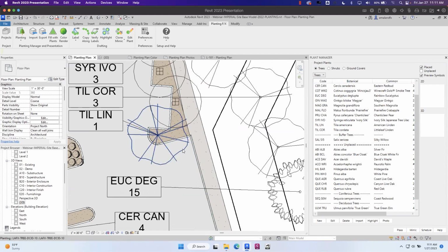Basically, if you open up the family, this symbol does have a hierarchy in it. I just need to make sure that hierarchy now gets translated when the family gets inserted. I'm not sure why Revit would not have automatically picked up those line weights in the family already in any plan, but it should have, and we're working out what's missing and why it's not doing it with our families. Coming from AutoCAD development, it's always hilarious when something as simple as editing the layer in Revit is wildly complicated.